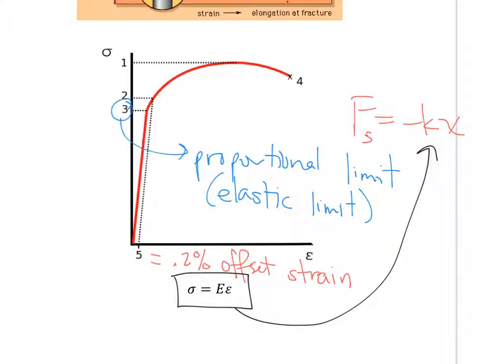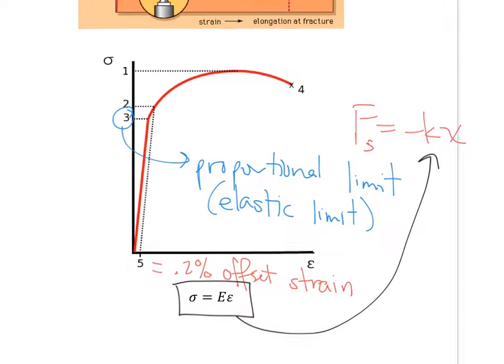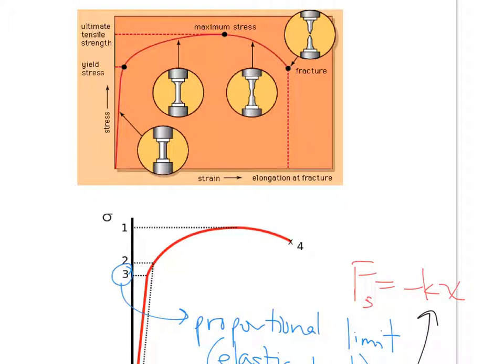Now again, once you pass the proportional limit, as you apply a little bit more stress, it changes shape a lot suddenly. And at 2, you reach what we call the yield strength. This point here is when it starts to yield, meaning it starts to really, really, really narrow. And then you'll see what's occurring here. Okay, you're going to see it start to yield and it starts to stretch a lot until you reach this fracture or this necking and then the fracture point.